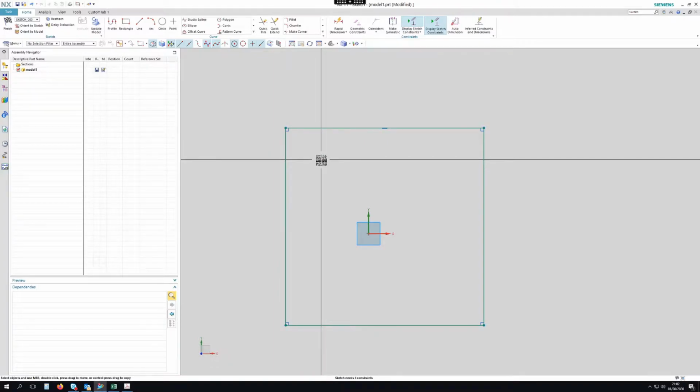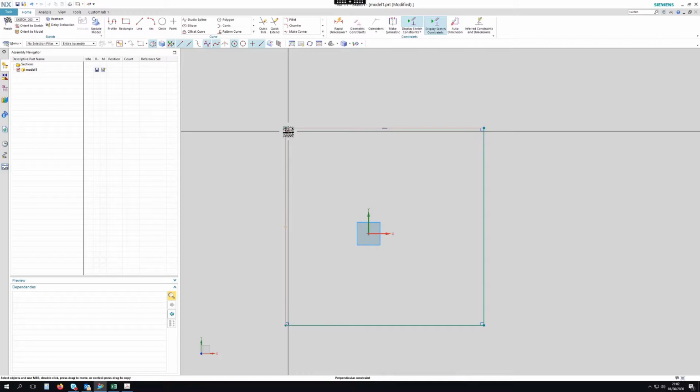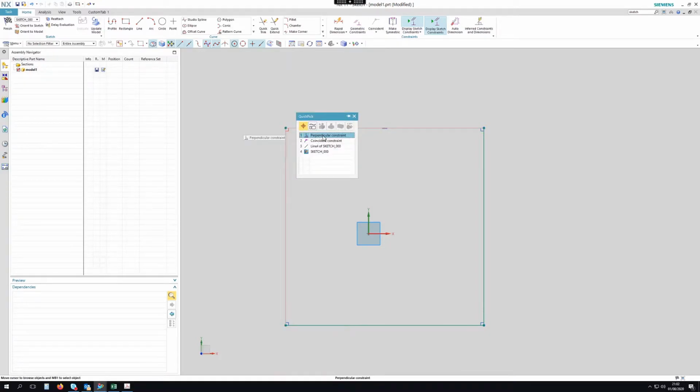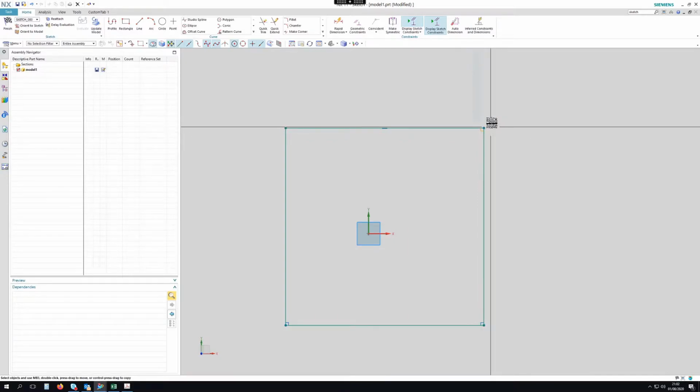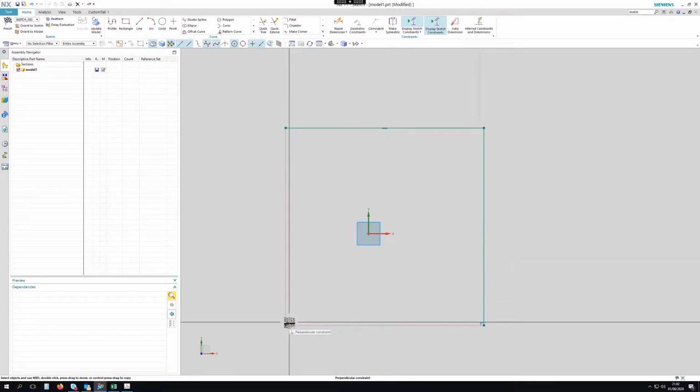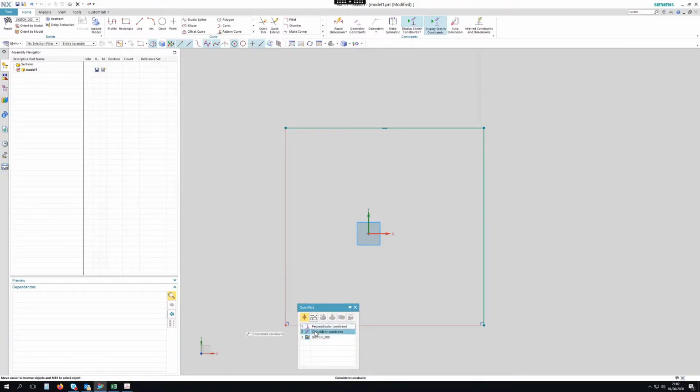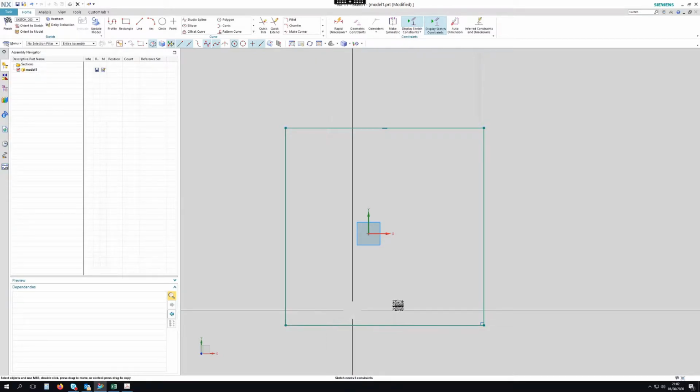There is a way of changing this in the system to put in the constraints that we want, but for now I'm just going to delete these 90-degree constraints by highlighting them and deleting them. If you do it fast enough you can delete it straight away. If you highlight there and stay there, 3 little dots appear and then it gives you the option, if you left click, on what's at that location, and it's this constraint we want to delete, so we can delete that one.